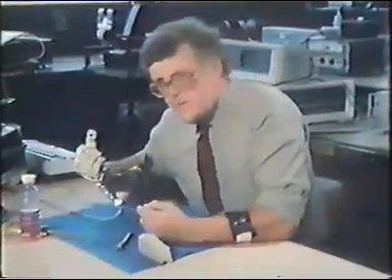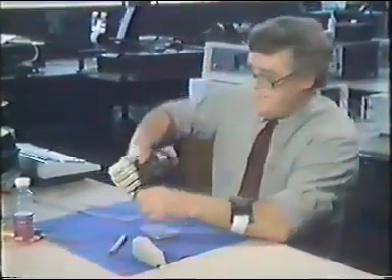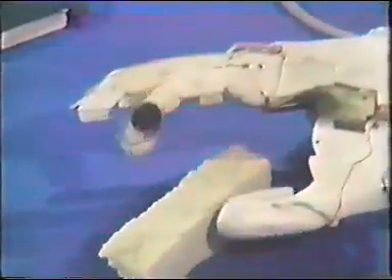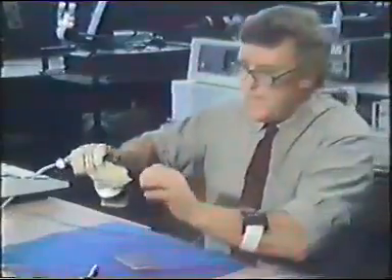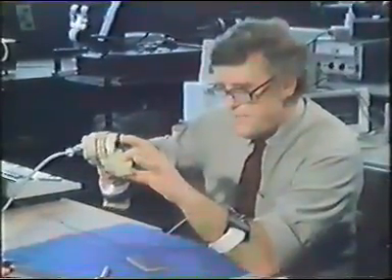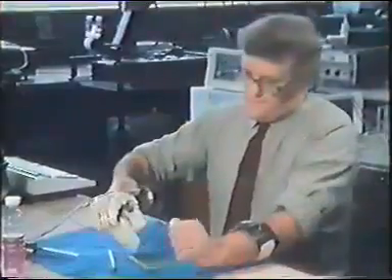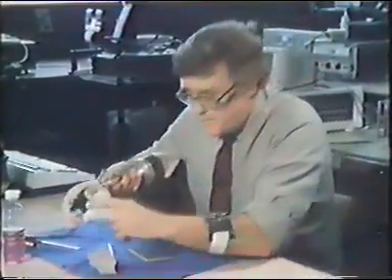There's an even more interesting sensor on this, and that's here in the thumb. All it is is a microphone underneath this piece of Velcro. When I want to pinch something in between the fingers, I can pick up this piece of sponge like that, and as I pull this piece of sponge out, or attempt to, the sound is transmitted from this sensor into the computer. When it hears the sound, it automatically tenses up the hand to stop me from withdrawing the sponge. In other words, it's a complete feedback mechanism. No signal from my hand is affecting it. And I can simply open the fingers and let it drop. There's another sensor here on top.